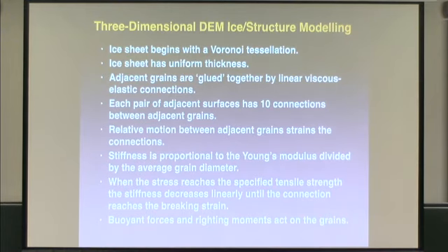How big are the tessellation elements? How big are the elements compared to the ice sheet thickness? Because it's 3D, and you're going to model an ice sheet that's a kilometer long and half a kilometer or so wide, the best resolution I can get is 2 or 3 meters average diameter, compared to, say, a 60 or 90 centimeter thickness. Quite a bit more, yeah. I'd love to go down to a meter, but I can't do it right now.